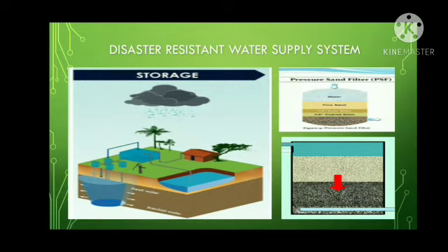Next, in the storage process, after passing this water through a simple sand filter, it is infiltrated into a shallow saline aquifer through a ring of infiltration wells. An aquifer is a portion of groundwater that holds a large amount of water. So this creates a floating lens of improved quality water underground. The freshwater lens stays intact underground, as you can see in our figure, because the water mixes only minimally with inherent brackish or saline water.